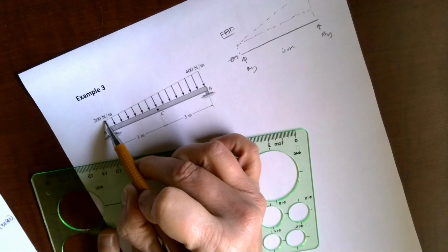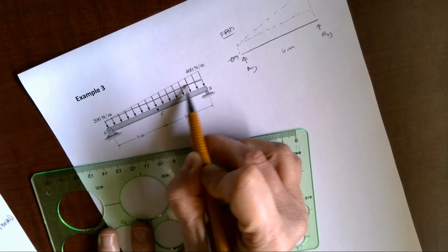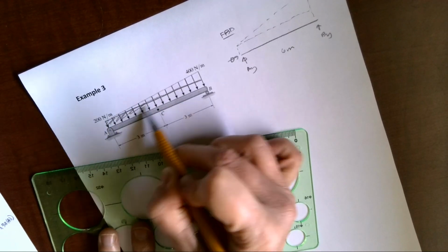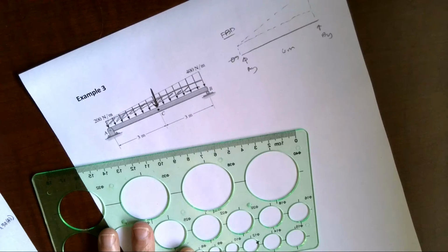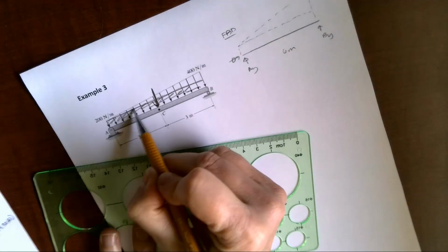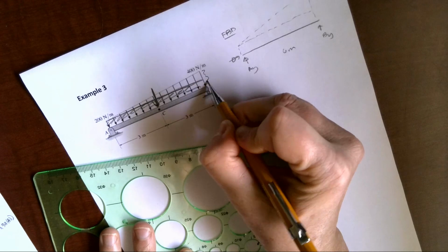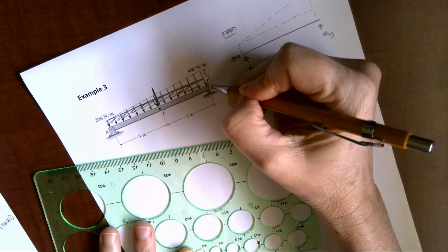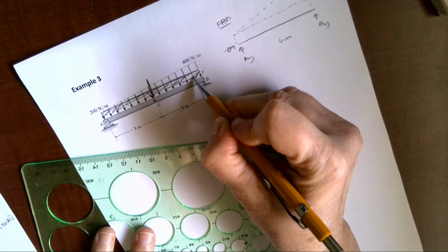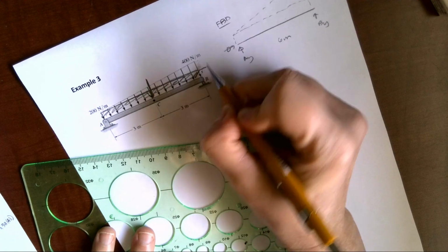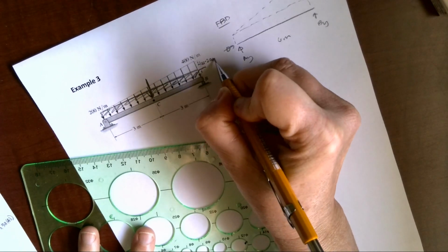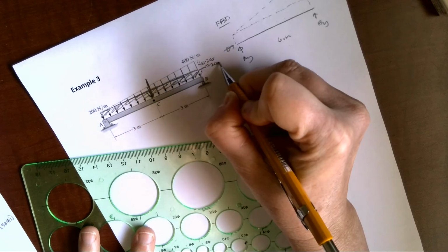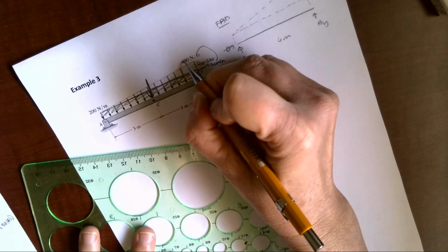I can draw this across, and I can see that I have a rectangle, and a rectangle will have a point load right through the centroid, and then I'm left with a triangle. And when I look at this, this whole height is 400. Let me erase that squiggle. But I've already accounted for the bottom 200 newtons per meter. So I'm going to have 400 minus 200. 200 newtons per meter is my new height of the triangle.